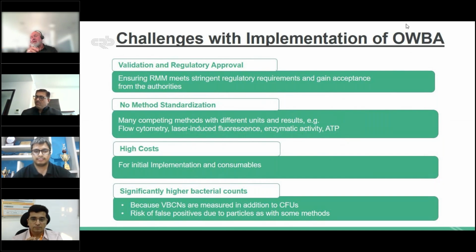That's one topic. And the other reason for this technology is that we can gain a full picture of the situation. So we can measure downstream of reverse osmosis. So we can identify immediately a change in the microbiological water quality and can act immediately, doing a hot water sanitization or something else. So this is another big advantage.